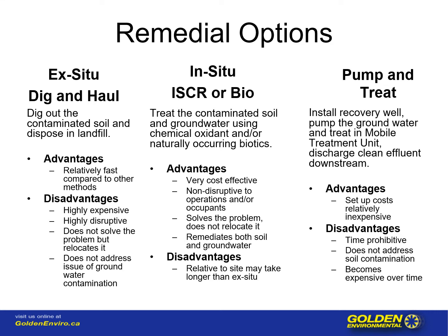The other consideration is porosity. In order to achieve saturation in the contaminated zone, we also must understand the porosity. This is the volume of space between soil particles. We must saturate the zone in order to bring the contaminant into the aqueous phase so that the oxidant or the microbes can degrade it. Part of this is understanding how much pore volume, how much space between the soil particles there is so that we can fill it. These are all part of the considerations when developing an in-situ remediation plan.